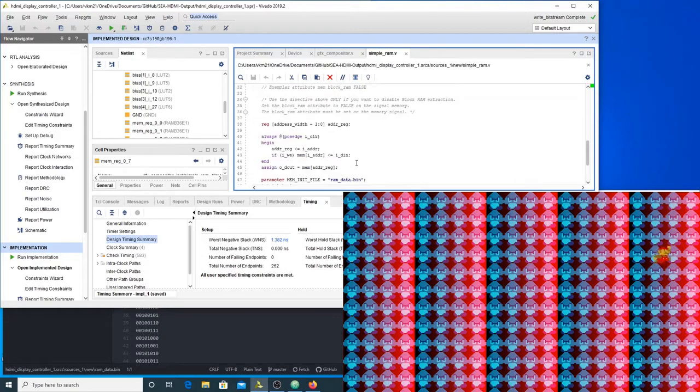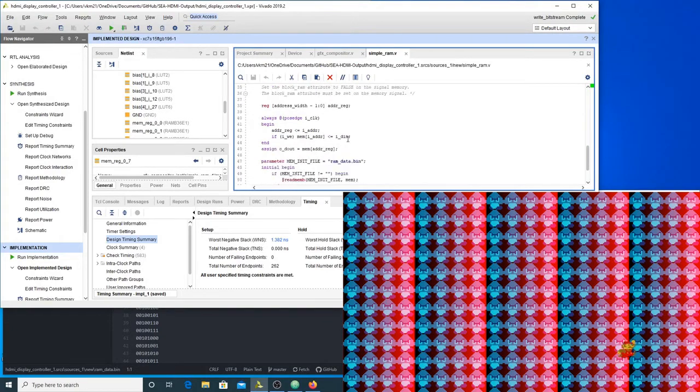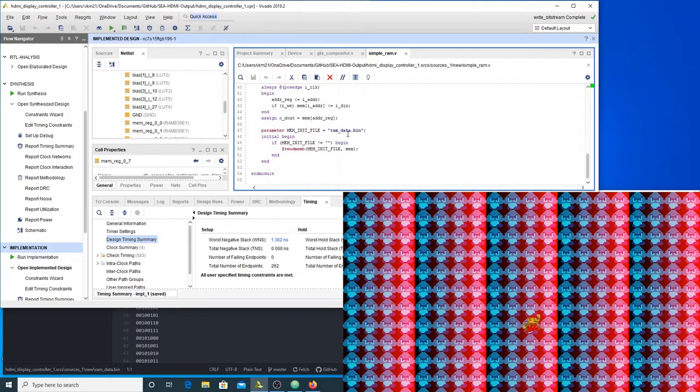And so I was at the point where I was able to build in this memory, but I wanted to put some data into it. It turns out there are a couple ways to do it, but the simplest way I thought was you can have it set up so that during synthesis it's going to read a file and then put that data into memory. So that as the FPGA starts up with your design, it will actually have data in memory already. And that's just a clever shortcut for now. Eventually I'd like this to be loaded in dynamically from a program, loaded from a CPU that's on the same board as the FPGA, but you have to go one step at a time. So it seemed like a good way to start.